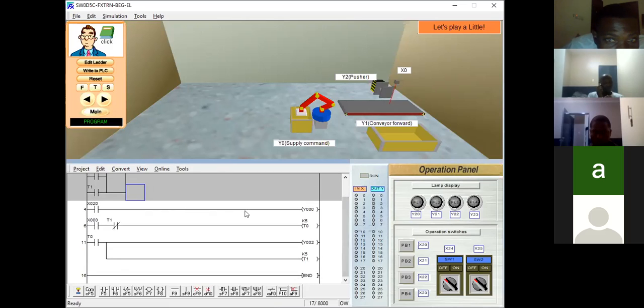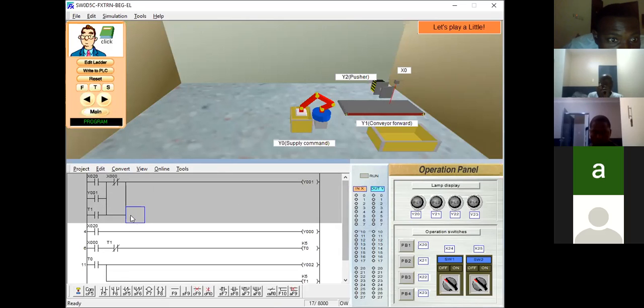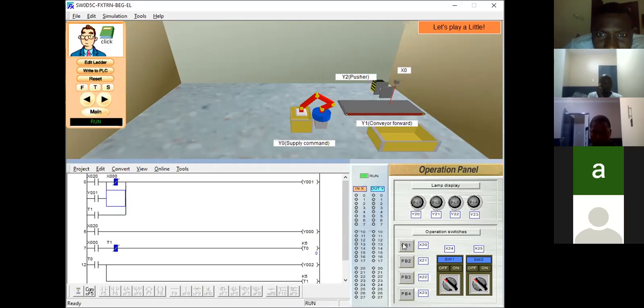Great. So you can remove the other ones because we want it to be outside this place, not to follow the same round. Okay, so we convert. Let's see if this retains our conveyor, then the program is finished. Okay, conveyor still moves back. Can you see that the conveyor continues to move back? Then let's use the same signal to now supply our command again.